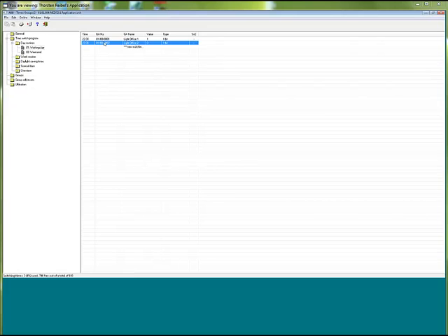So you see, at this time, with this group address, I switch on, in this case, light office 1, or I switch off light office 2. And so on. 800 switching times can be programmed. It's a lot. So what else do we have to do? Day routines we have to assign to week routine.